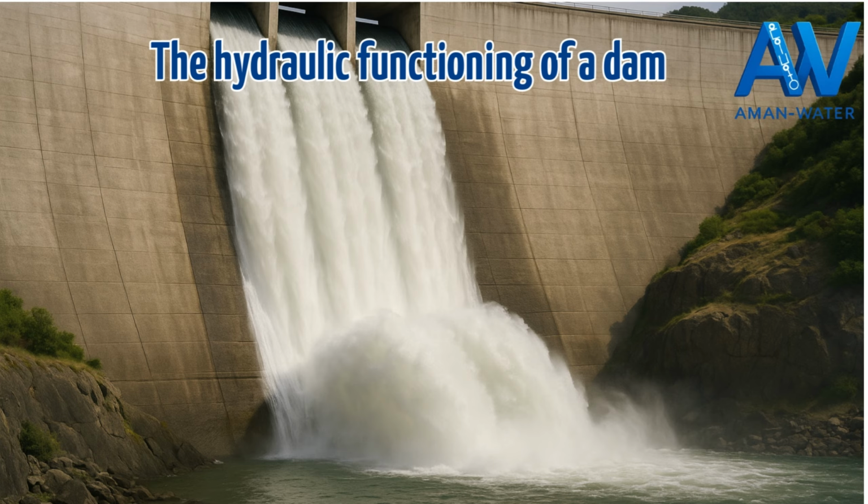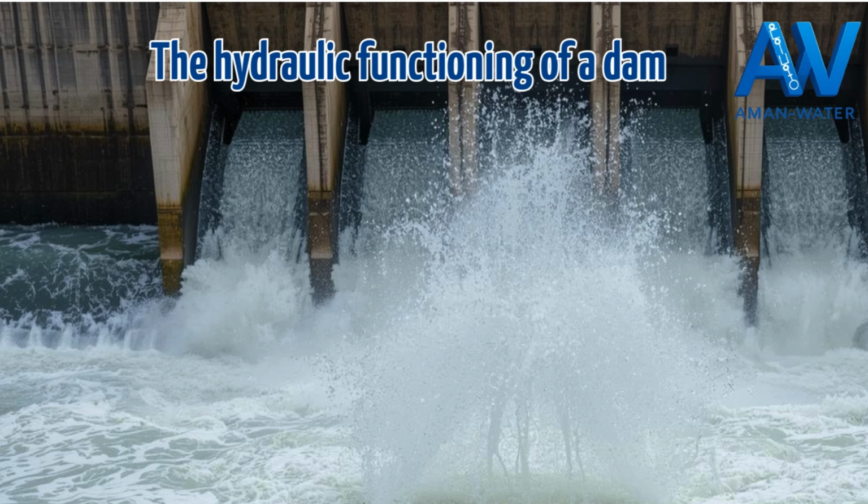When a flood arrives, the spillway becomes the key element. Its role is to evacuate excess water before the dam is exceeded. Too little evacuation and the water rises dangerously. Too much evacuation and downstream areas are hit by a strong wave. The spillway allows controlled flow even in extreme situations. It is one of the most sensitive parts of the dam because uncontrolled overtopping can quickly erode the structure.